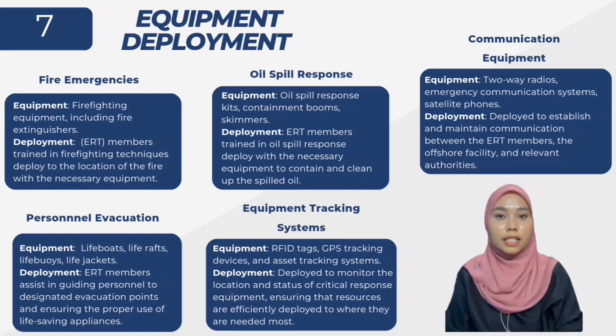First one, fire emergencies. For the equipment, firefighting equipment including fire extinguishers, hoses, water monitors, foam systems, and firefighting suits. For the deployment, emergency response team (ERT) members trained in firefighting techniques deploy to the location of the fire with the necessary equipment. Fixed firefighting systems may also be activated.